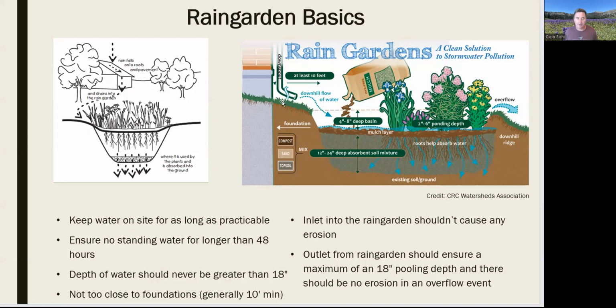Okay, so very important in these systems that we do not have erosion going into that system, because if we've got a heavier clay soil and we get infiltration of that clay into this system, we're going to reduce the amount of water holding capacity in that system.